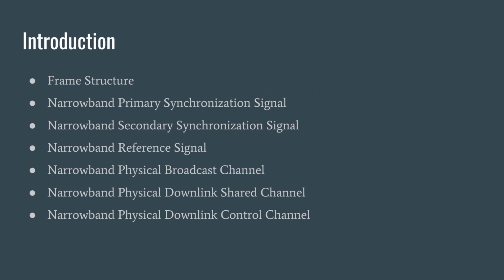First, we're going to give an introduction to the concept of narrowband IoT. We'll go over narrowband frame structure, primary sync signal, secondary sync signal, reference signals, physical broadcast channels, physical downlink shared channels, and physical downlink control channels.